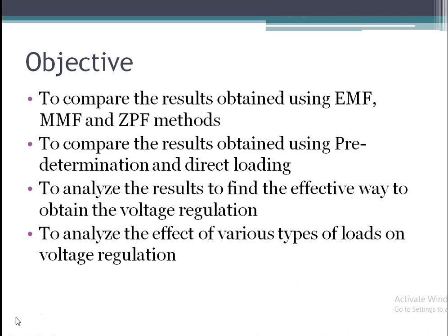Find the difference and analyze which method gives you an effective way to find the voltage regulation. Also, for the load test you are using three types of loads, that is inductive, capacitive and resistive loads. Our objective is to analyze the voltage regulation obtained for the three types of loads, and why there is a difference in the performance of the machine for different types of loads. So this is what we are going to study in conducting this experiment.